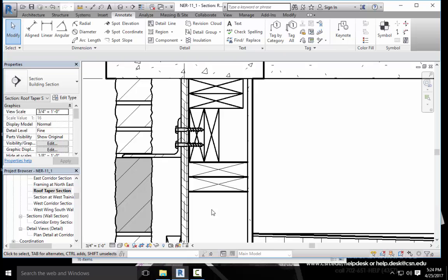All right. So what makes a medium line medium and thin line thin? This is part of Revit over which you need to have full control. After all, your biggest challenge will be getting your plotted sheet to match your old CAD plotted sheets. Specifying line weight is crucial. Specifying drafting line weights. In CAD, you wouldn't dare to draw even a single line if you didn't know the proper layer on which it was being drafted. Why should Revit be any different? The objective of the next procedure is to investigate where the line weights are stored and how they relate to the lines you're drawing. On the Manage tab, choose Additional Settings, Line Styles.